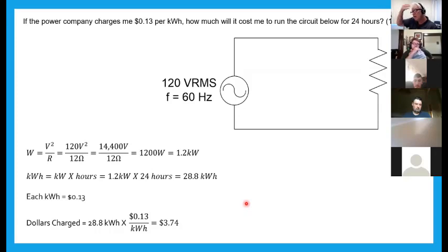And in doing that, somebody says, well, look, I'm thinking about getting this water heater or this, whatever this device is, a motor, a fan, whatever it is. And you need to kind of give them an idea what it's going to cost. This is what you do. It's like, how long is that thing going to be on every day or a month? And with those kind of numbers, you check with the power company, see what their rate is. You can give them the cost of using that device for the need that they have over a period of time.